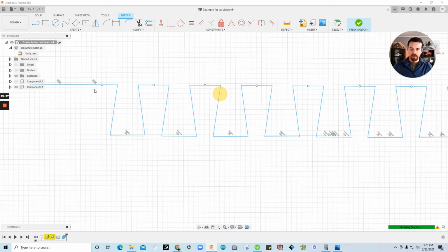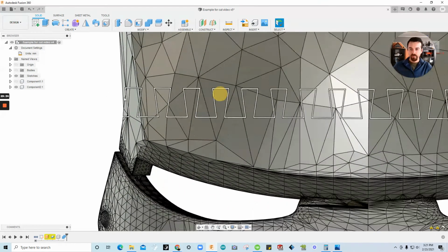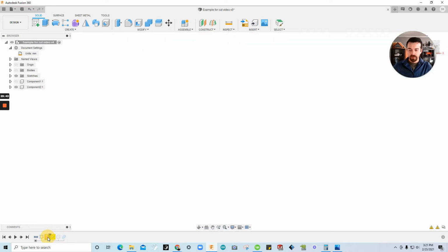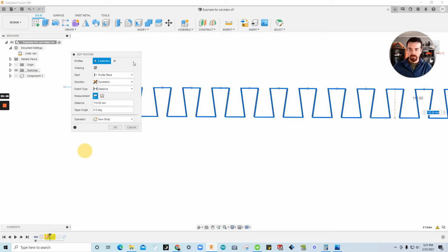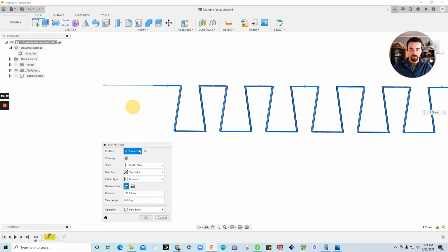Let that load up, and we'll see. Alright. So as you can see, we're faulting because we've made some changes. I'm going to go ahead and roll the design history back to each one of those. Click on the yellow fault and do Edit Feature by right-clicking, selecting Edit Feature. As you can see, we've selected all the lines, except for our new one. So while I'm in that selection, I'm going to go ahead and click that as well. And click OK.